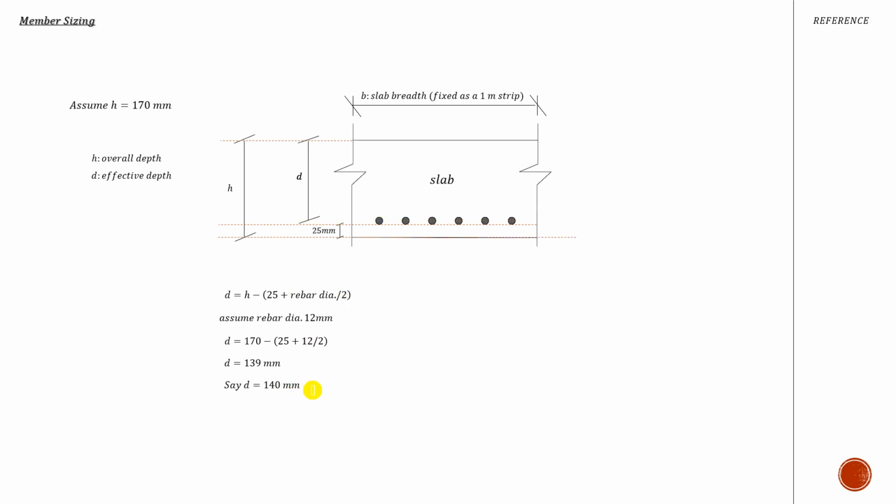Right. Another important term is the fire resistance. It's measured by using this axis distance, half of the diameter up to the extreme bottom. And referring to this code, table 5.8, you will see that in my question, they did not specify the duration of fire resistance, but I'm assuming it will resist fire for 1 hour. That's 60 minutes.